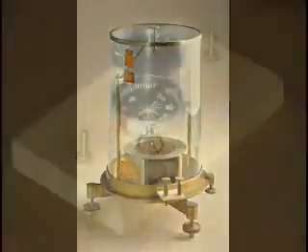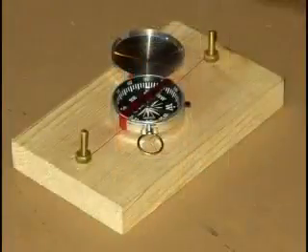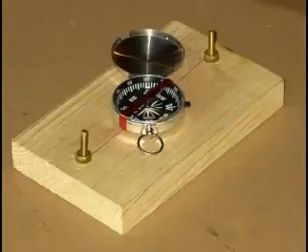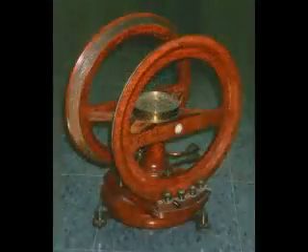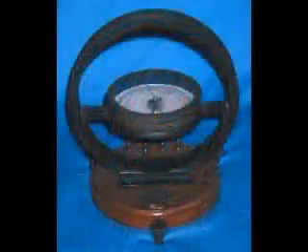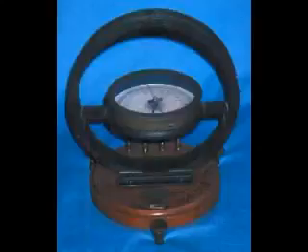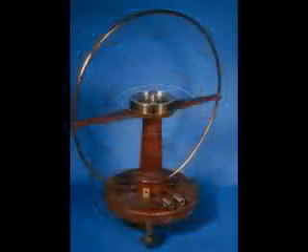A very simple galvanometer may be made from a magnetized needle, such as the needle in a magnetic compass, positioned within a coil of wire carrying current. Current through the wire coil will produce a magnetic field which will deflect the needle from pointing in the direction of the Earth's magnetic field. Current meters like this were called tangent galvanometers. They were used in the 19th century to measure current.